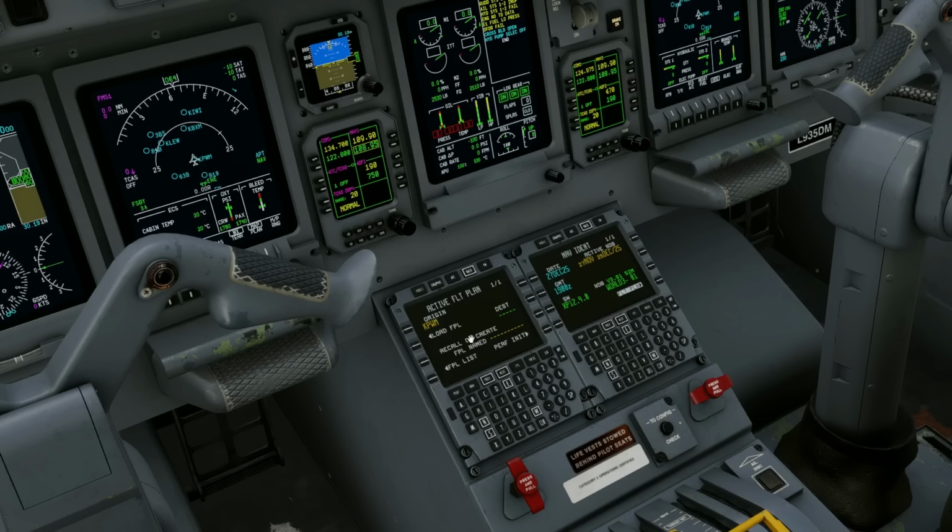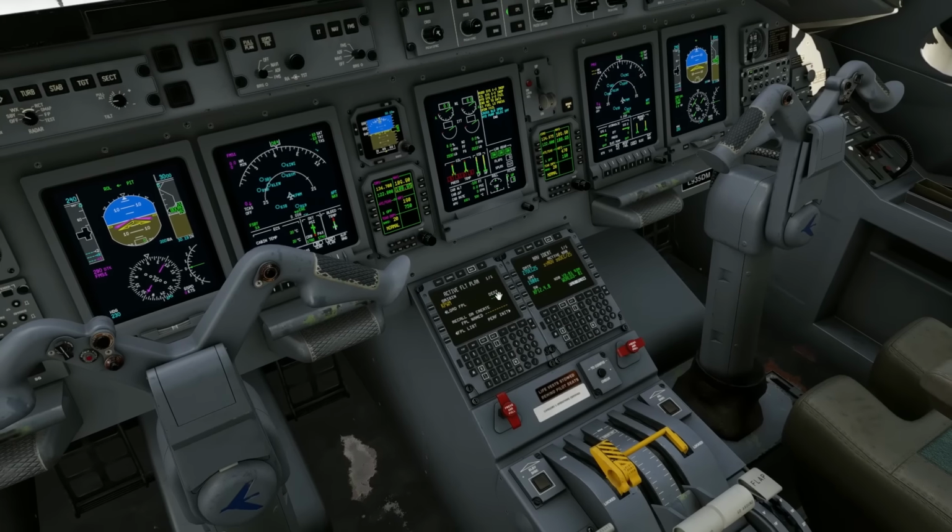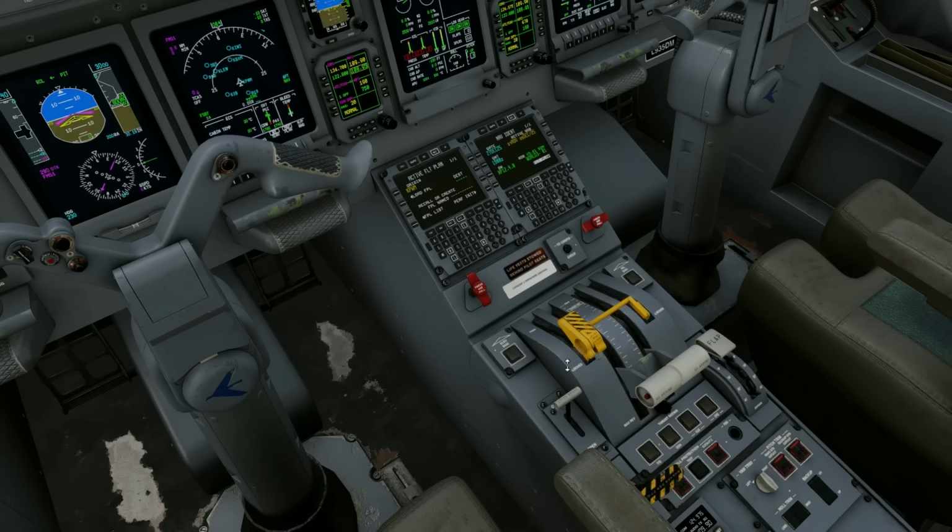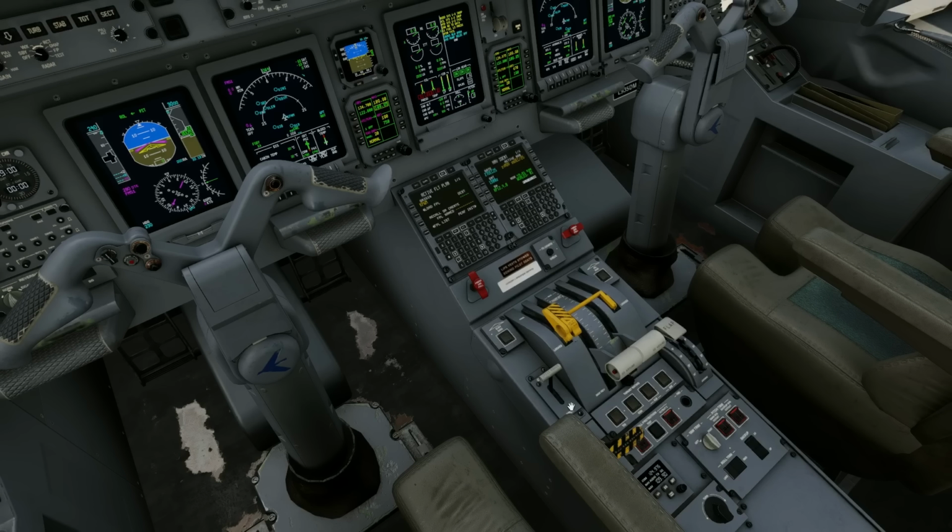One of the newer stars of the show, and something very cool that we have now, is the Gust Lock. So like I said, the aircraft has unpowered pitch controls. Elevator control is completely unpowered, and it is directly connected to the tail via cables and pulleys. So on the ground, we have to lock the elevator in order to make sure that it doesn't flap around in the wind, incur damage, and smack you in the knees, and all sorts of stuff.